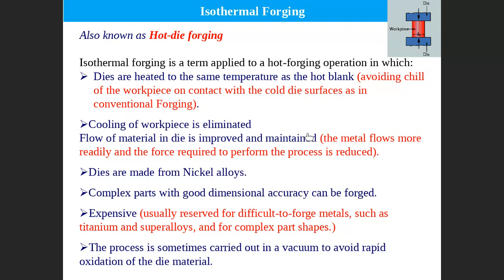However, this weakens the die; the die becomes weak. Why? Because when heating the die up to the same hot temperature, the die material becomes softer. Definitely this leads to shortening the life of the tool.